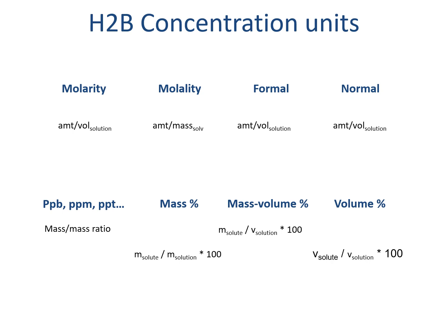So we care a lot about water, but we also care a lot about what's in our water, and depending on what it is, we may talk about concentrations a lot of different ways, depending on what we're measuring. The top 4 units on this page are all based on mole units, and they are particularly useful when an analyte, a thing that we're looking at, will undergo a chemical change. For example, it's really helpful to know the molar concentration for carbon dioxide that's dissolved in water, because it's always going to be in an equilibrium defined on a molar basis with carbonic acid.